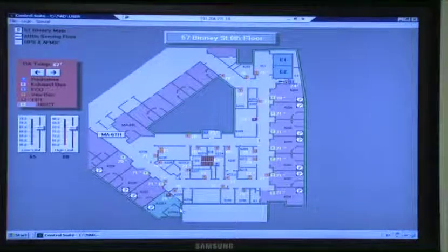Okay, I don't get it. Supposedly it was a change in the beginning of the project where DPH wouldn't allow them to put a negative room inside of a positive HCT suite. So they said, well, keep your ante room, keep everything, but make it all positive. So you can make a buffer room, you can make it positive, but you're going to have to put a buffer ante room and all that stuff, which all flows the same way. It doesn't make a hill of beans sense to me at all.